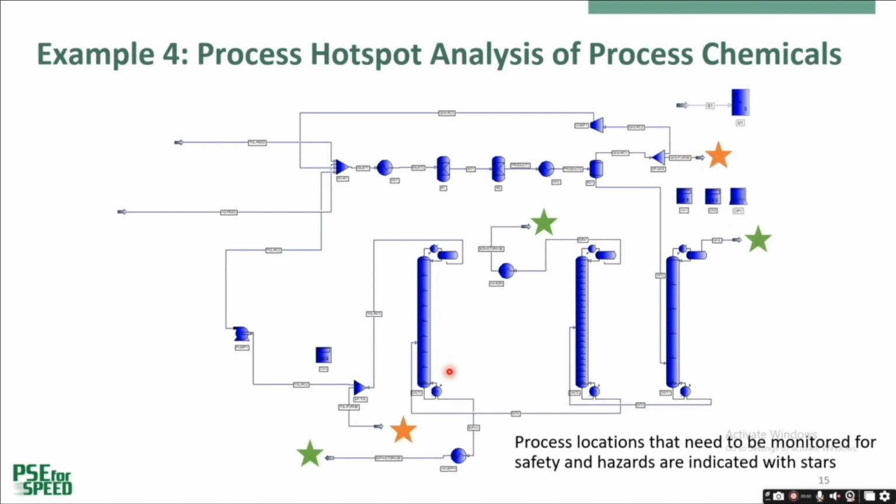The purged gas stream is represented by the orange stars. Benzene, toluene, and 1,1-biphenyl must not go out through these streams. Their concentrations need to be carefully monitored. The pipeline containing high-pressure compressed gas is represented by yellow stars, and the pressure must be monitored.